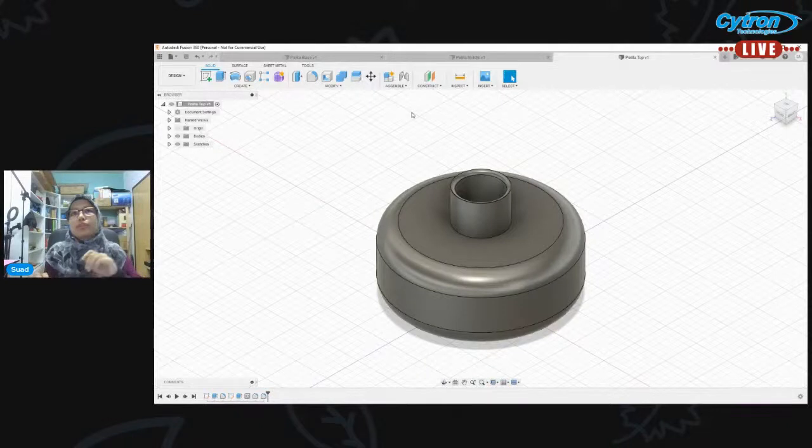If you want your 3D printer to read the 3D modeling that you have designed, you need to have the file in G-code. But before we convert it into a G-code file, we need to have an STL file that we slice in Cura. Then Cura will convert the file into the G-code file that will be understood by your 3D printer.